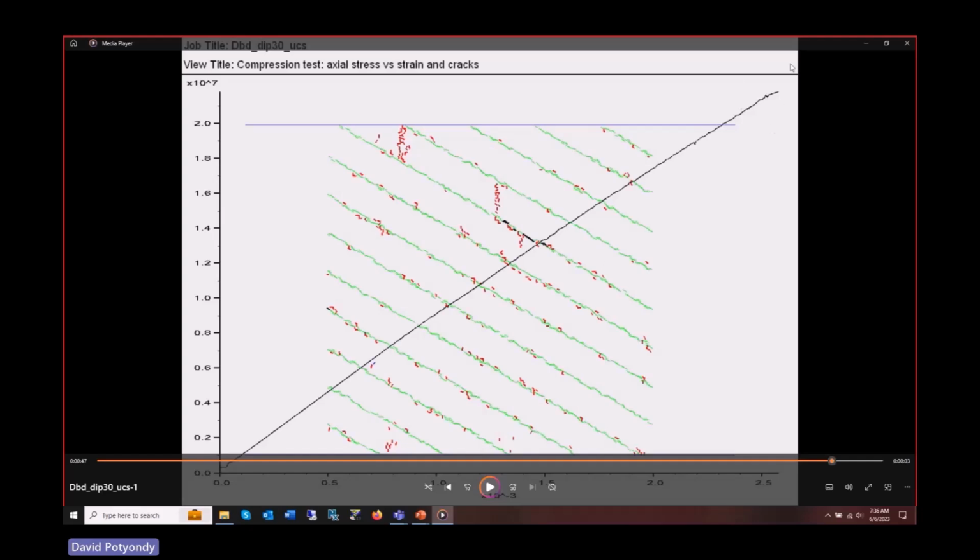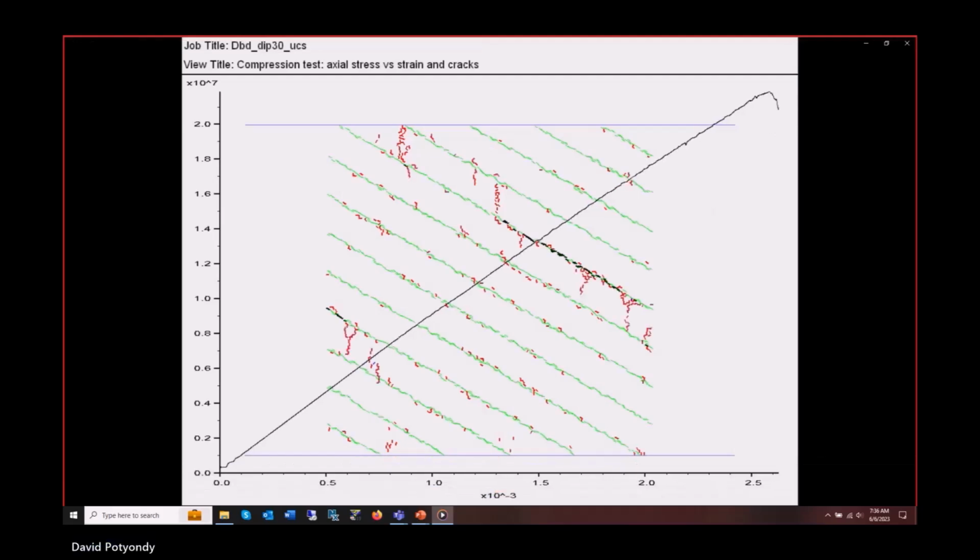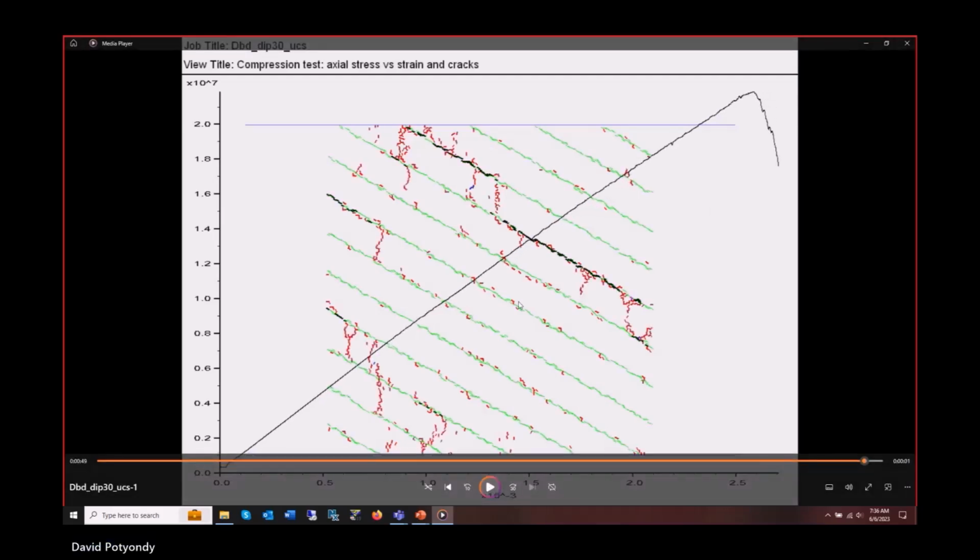This is just beginning. Watch, this is going to continue to drop now. And there we go. So basically this thing started, it caused this to rupture, it caused this to rupture. Now we have a mechanism whereby the whole top half is going this way, the bottom half is going this way. We've effectively created at a macroscopic level a shear fracture in this system. And now, of course, it's not carrying as much stress.